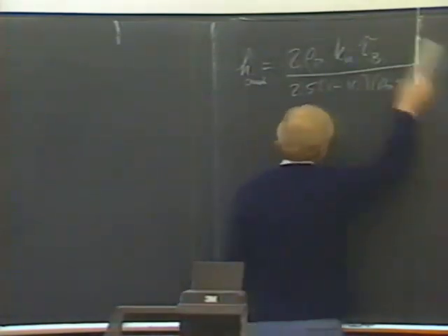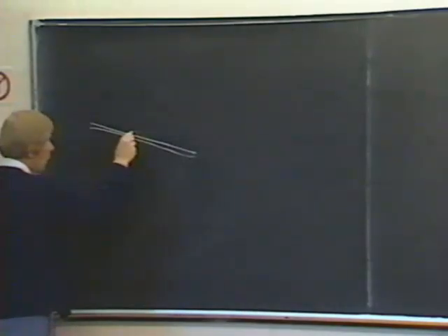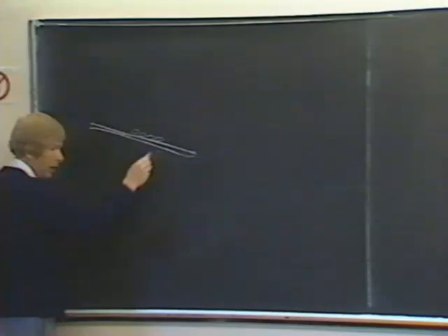One of them is that if we look at the clay particle edgewise, let's say something like this, the water molecules right near the surface of the clay are attracted by van der Waals forces to the clay surface. They're also attracted by hydrogen bonds, which I'll describe in just a minute. The second is the thermal motions of the molecules in the clay surface are much less than the thermal motions out in the fluid.